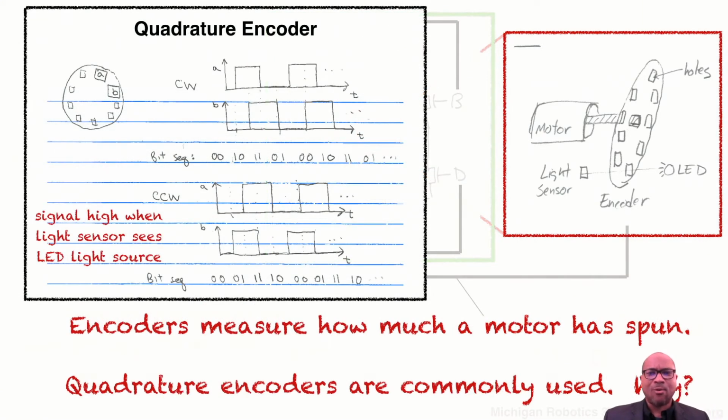We should note, and I won't cover this very much, this is the extent that I'm going to cover it: we can use a number of different things to do proprioception. One common choice is the quadrature encoder. That quadrature encoder essentially has an encoded disk, and the sensing usually goes from light to dark, or from occluded to non-occluded in the case of the light sensor that's shown here.